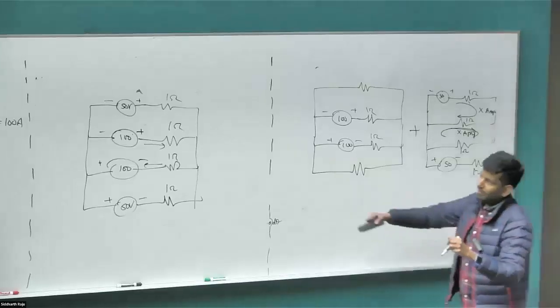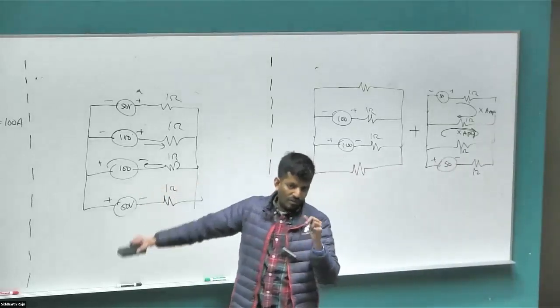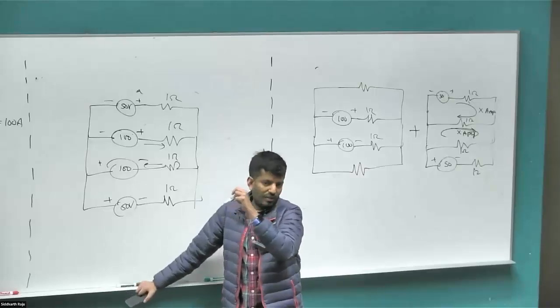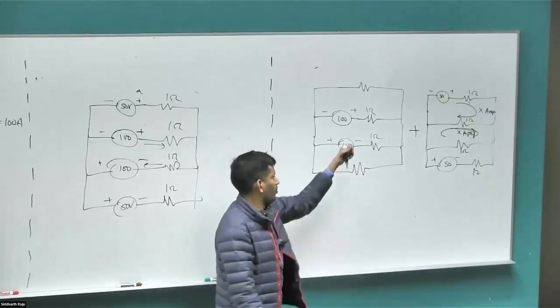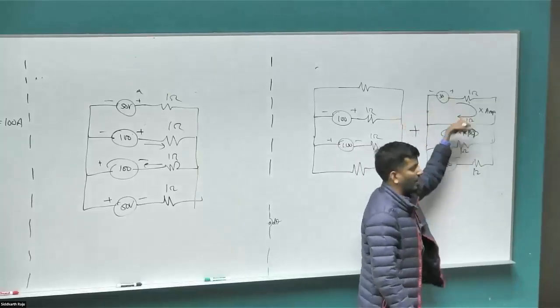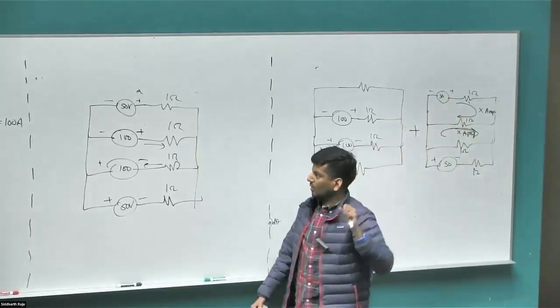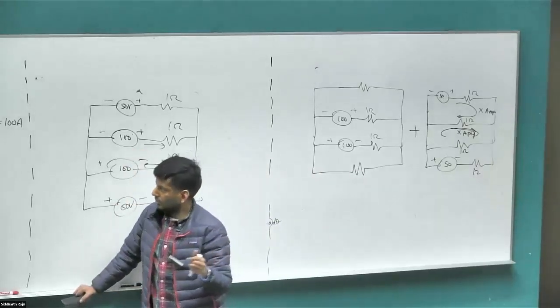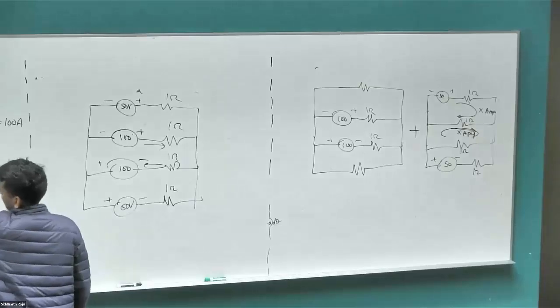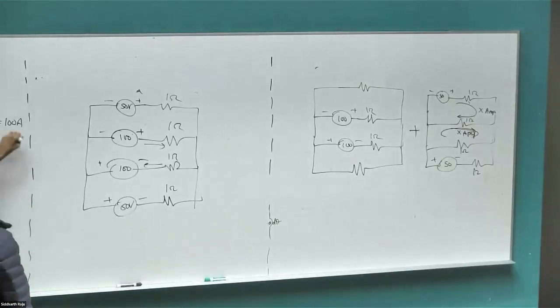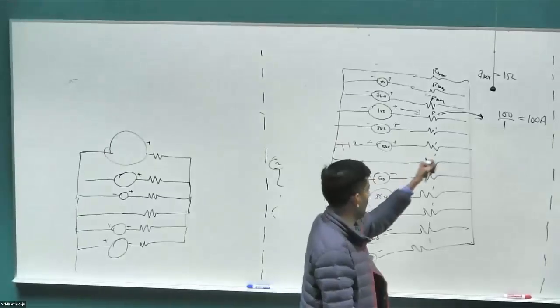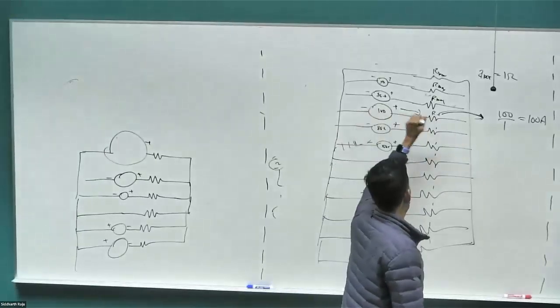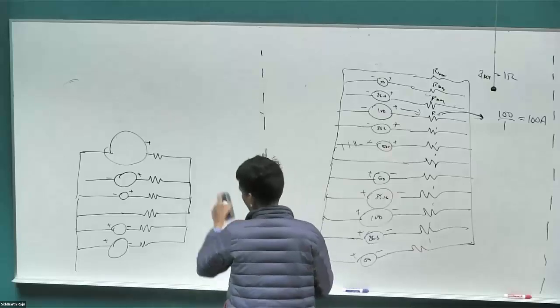So as long as we have a voltage distribution that's symmetric, for every positive voltage that we have in the circuit, if we have an equivalent negative voltage, the current contributed due to those voltage source pairs would cancel out. At the end of the day, leaving only the current due to the primary voltage source that we considered for the particular loop. So the answer Ben gave is perfectly correct. Take whatever the voltage across this is divided by the resistance, that will be the current. There's a little bit of intricate detail going on in the background, but luckily for us, these are extremely symmetric, so it simplifies our life that the current is just the voltage divided by whatever the resistance that we have there.